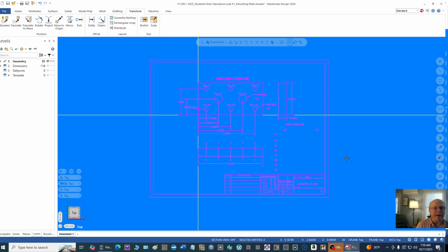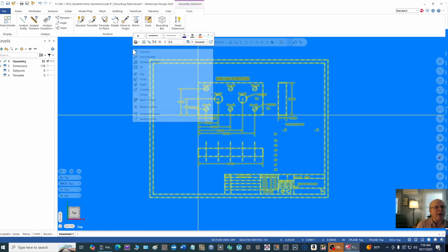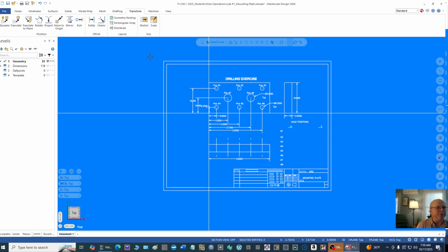And you say, well, why did everything turn pink? Okay, that is just, in my opinion, a pesky thing that Mastercam did. I'm sure they have their reasonings, but in order to get the colors back, I'm going to draw a box, left click, hold it down, draw a box around this, and I'm going to right click up here and go to clear colors. You see there's this drop down, okay? And you hit clear colors and everything will go back to white again.